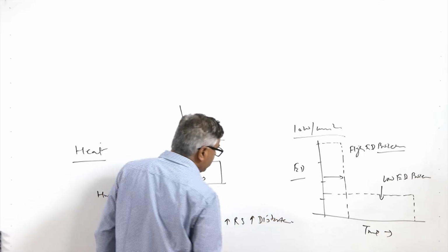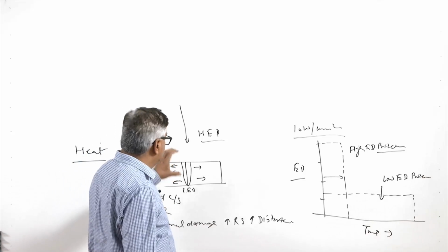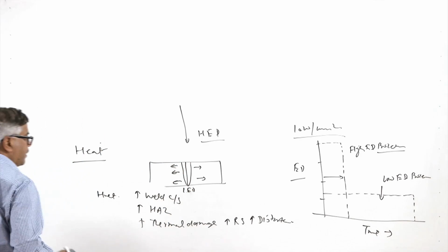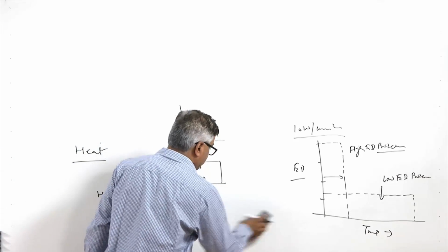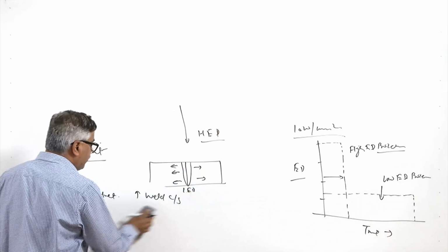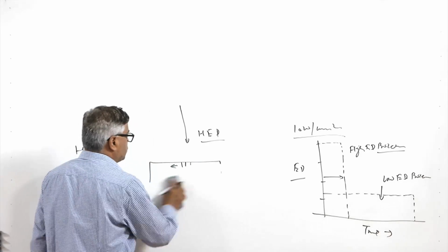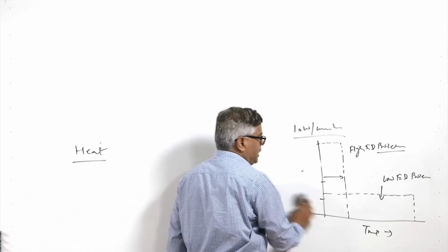So, all these problems will be more. It is always good that the joint is made using as little heat as possible for facilitating fusion, and for this purpose high energy density processes offer much better results in terms of the thermal damage to the workpiece due to the application of heat.